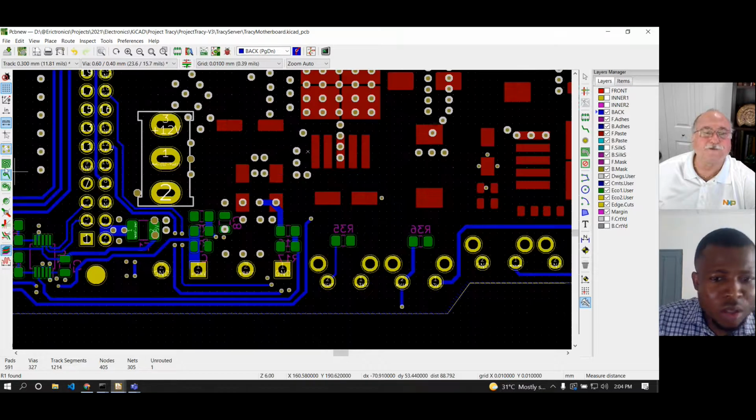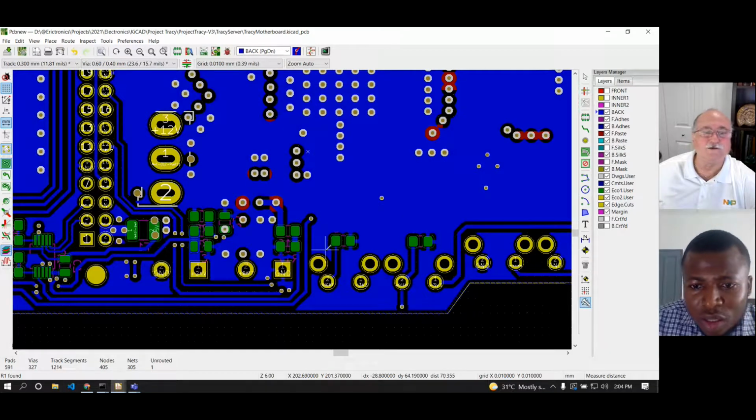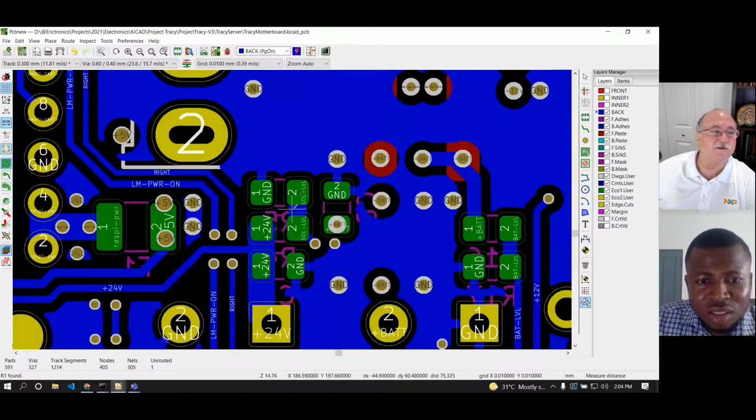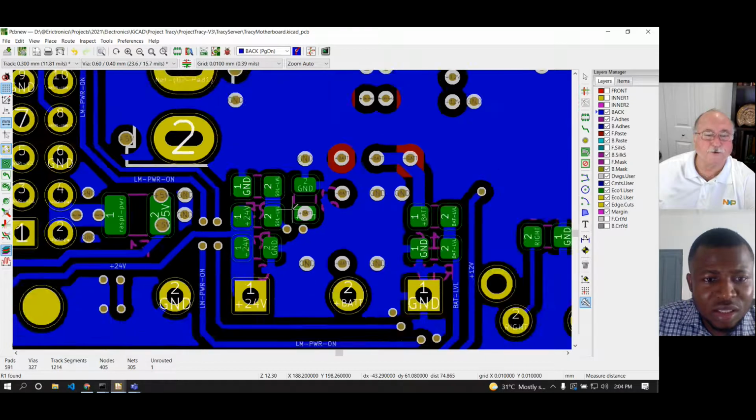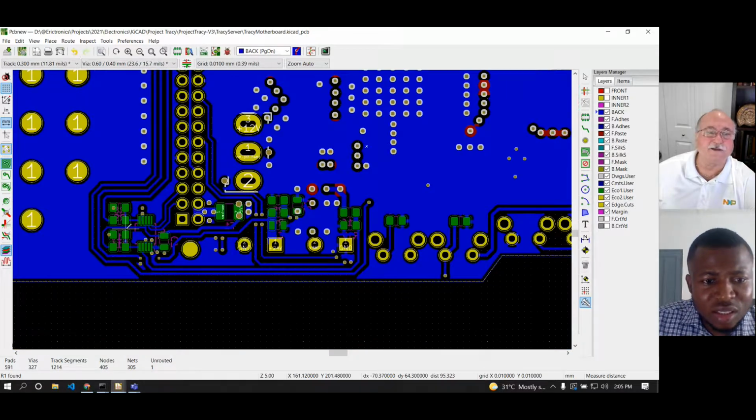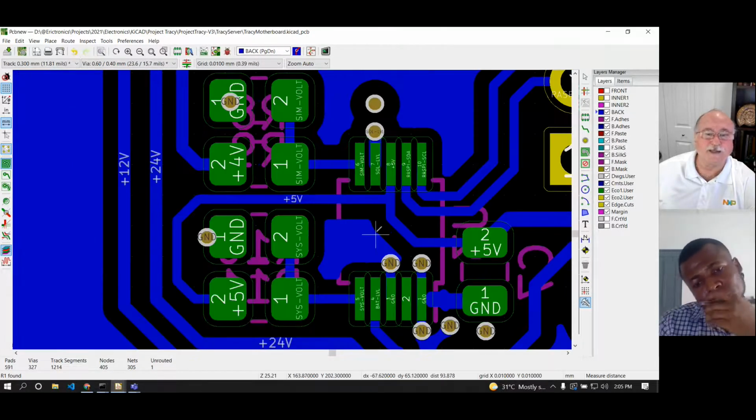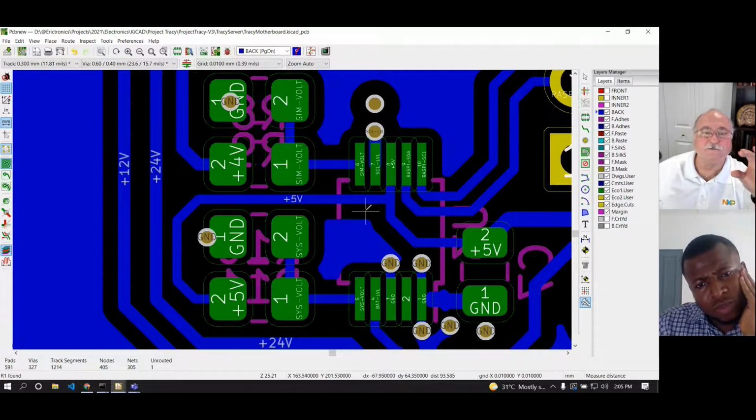You can't flood underneath those because the body of those components needs to see the energy that's in the dielectric between this. If it's a component on 1, it needs to see the energy between 1 and 2 in that space. So the body of those components need to see the energy.